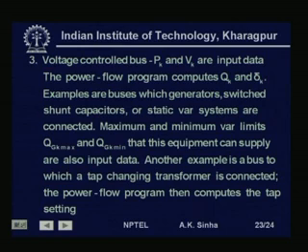Now, these bus bars, as I said, are generally generator bus bars or switched shunt capacitors or static var systems. So, bus bars which have these are generally PV buses or voltage control buses.